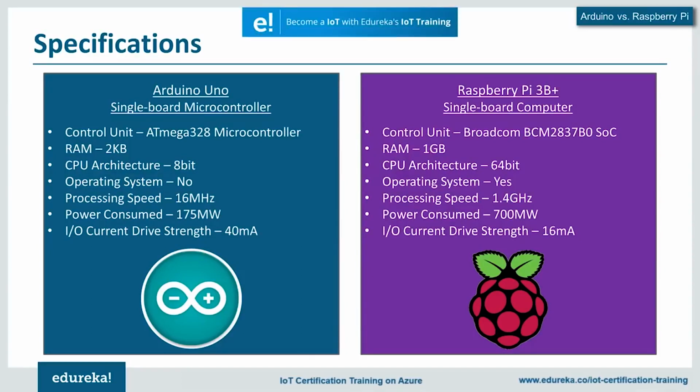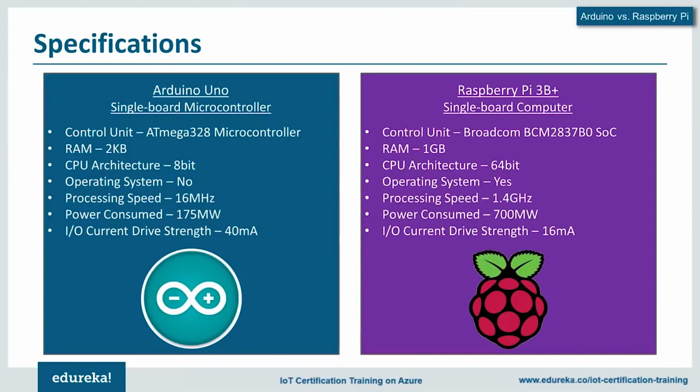On the contrary, the Raspberry Pi boards have a complex architecture of hardware and software. The Raspberry Pi 3B Plus comes with a powerful Broadcom BCM2837B0 microprocessor on a chip as its central processing unit, which runs on a 64-bit quad-core processor called the ARM Cortex A53, featuring a static RAM of 1 GB running directly upon the SD card storage at a clock speed of 1.4 GHz. Now, this microchip also acts as the graphics processing unit with the Broadcom VideoCore IV integrated graphics card built into it for low-power multimedia processing.